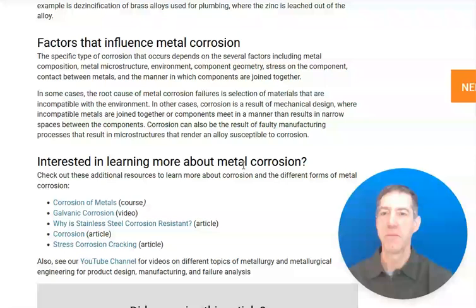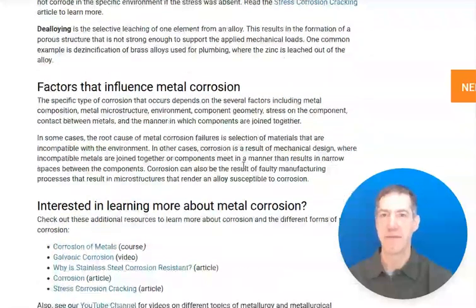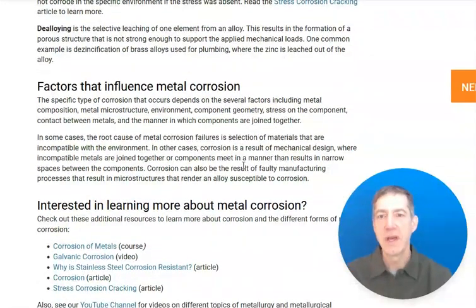There are a number of factors that influence whether corrosion will occur. This can be the selection of the material that's used in components. Also, design can influence it, whether dissimilar metals are selected and put in contact, or metal designs where we have crevices, designs where there are excessive stresses on the metal that can result in stress corrosion cracking. So there are a lot of considerations that need to be made to prevent corrosion from occurring, and having the guidance from a metallurgical engineer can help out.